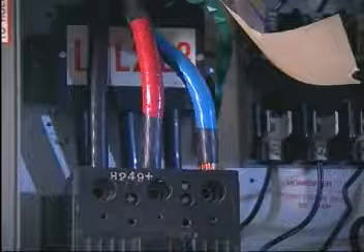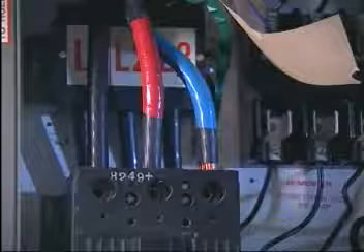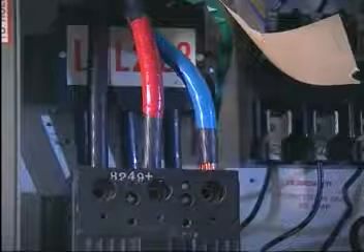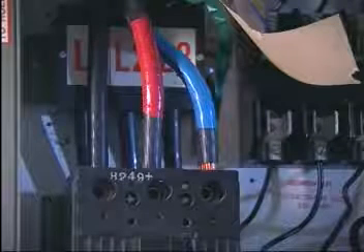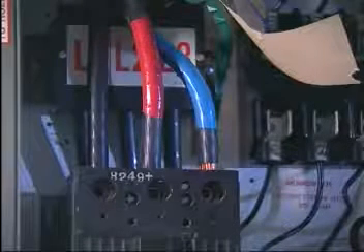The National Electric Code sets standards not only for the installation procedure for an electrical system, but also for the size of the conductor that's used in any given application. The maximum current that's expected to flow through the circuit determines the size of the conductor. Circuits that carry large amounts of current will require larger conductors, while those that carry only a small amount of current will require smaller conductors.